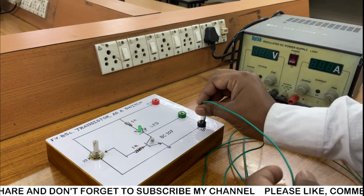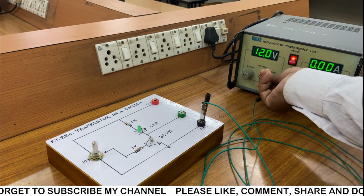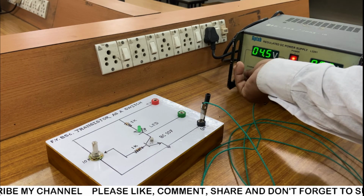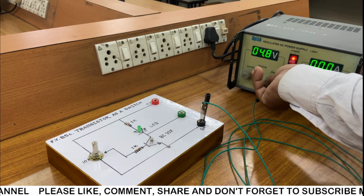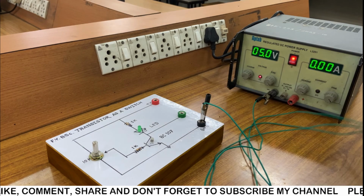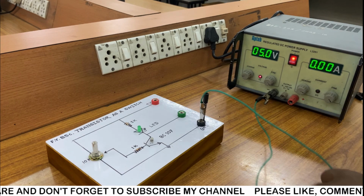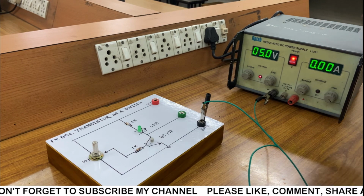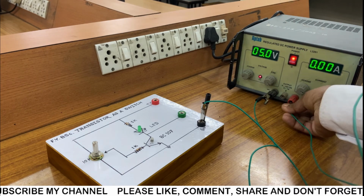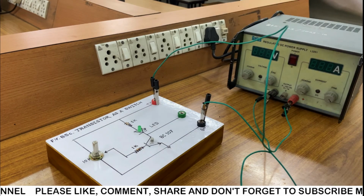Keep in mind, while setting the power supply, always keep the coarse and fine of the current at the maximum and middle respectively, and then adjust the voltage in such a way that the fine is adjusted for only 0.2 or 0.1. So this is a 5 volt adjusted; look at the fine button, I have adjusted the fine so that it becomes 5 volt. While doing the connection, we have to keep in mind that we have to switch off the power supply. So while making the connection, I am going to switch off the power supply and then make the connection. I have connected it to C.